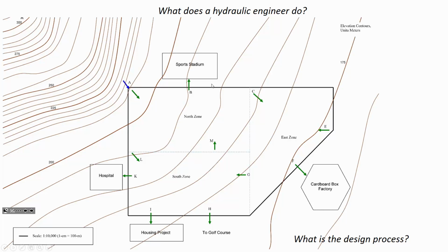And so you want your system to just barely give these people the amount of water pressure that is specified in the design requirements. And if you give them any more pressure, when you get to the end of this assignment, you're going to be really stingy with water pressure, because that's what costs money. If these guys want more water pressure, you have to make the pipe bigger, because that'll reduce how much energy loss there is through the pipe section.